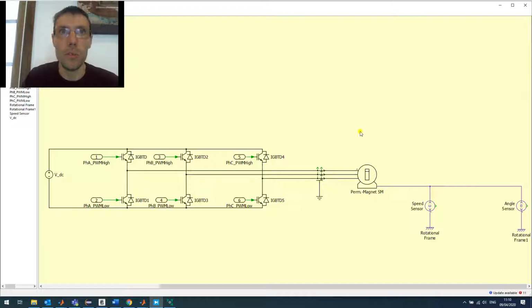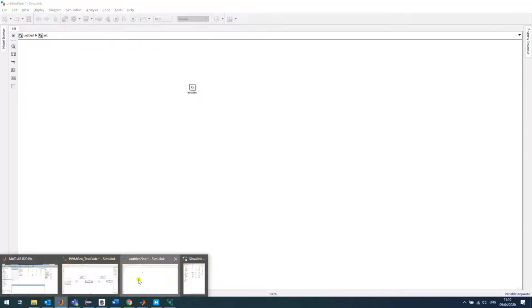You want to ask a torque or a speed to your motor, and the motor control software will generate the right PWM signal. So you have your motor, and you have your IGBTs that are set up in the three-phase half-bridge configuration. You have your battery, and then here you have all the control signals from the CPU that are calculated by the control software. That's pretty much it. That is very important. And so we're going to have a look at how we set it up with our interface and how easy it is to use. So let's start with going back to Simulink.